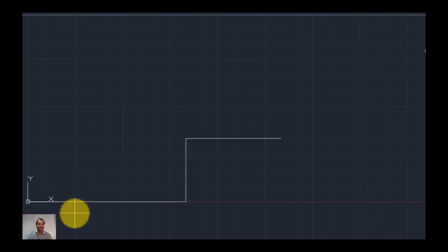X0, Y0. Okay. Let me check at 15 in the direction of 90. Okay. This is exactly 15. At 5 in the direction of 0. Okay. So why is it needed? Just by tracing the mouse over the line, we can construct the lines easily. That is why these grid lines we can redefine. Later we can draw objects using these grid lines.